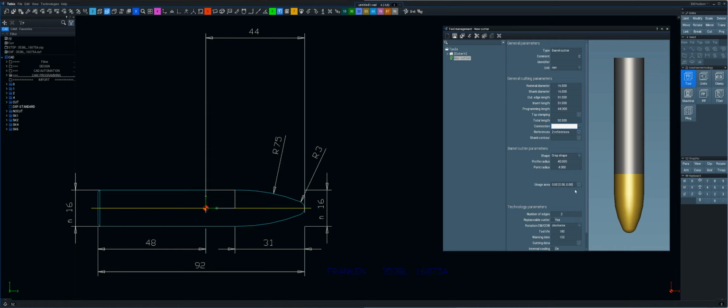Now we're going to go down to the cutting edge, the barrel cutter parameters. Tebis gives us 4 different options here. The first option is contour. Again, for the cutting edge, we can select the contour out here, but we would need to orientate the drawing into the proper position to the XY. We have a barrel shape cutter.